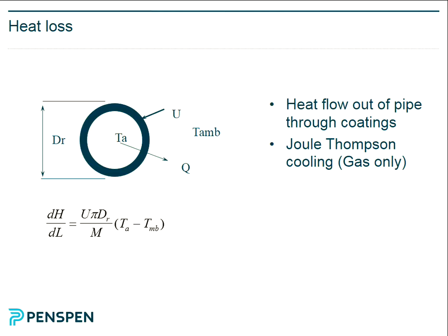So far we've only really talked about pressure. So the other thing is temperature, and pressure and temperature need to be resolved together, because the fluid properties which affect pressure and pressure hold-up are significantly affected by temperature. So you can't really consider one without the other. Temperature is very important too. Same with oil systems, even outside of multi-phase flow. Just an oil system, temperature is very important because the density of oil is so profoundly affected by temperature. So there's a whole thing with temperature you need to consider.